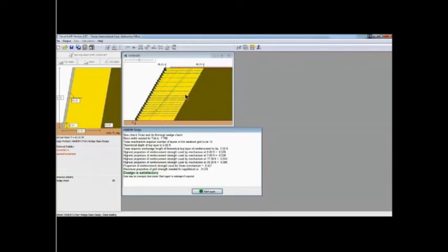But you can see we just ran hundreds of iterations or thousands of iterations of two-part wedge checks at varying angles from the back slope all the way up to the surface of the structure. But once we've done this, it says that we are okay with the internal stability. You'll notice the external stability note says foundation is assumed to be competent. Again, it is critical you design this with a global stability software and check it as well, such as our TensarSoil software or any other.